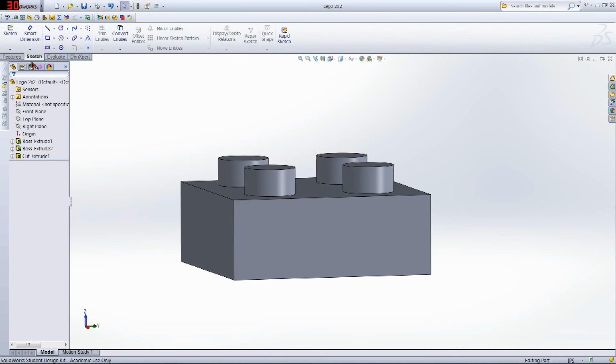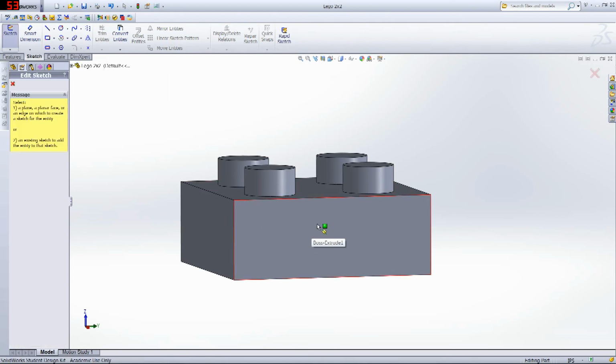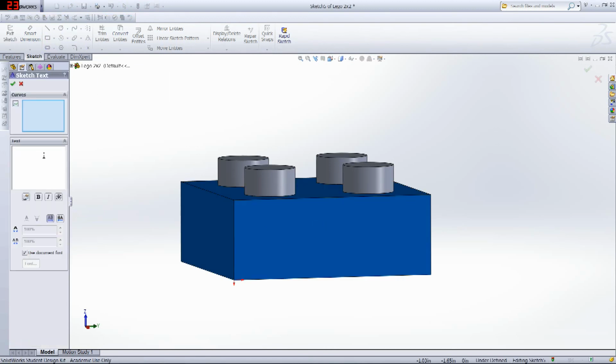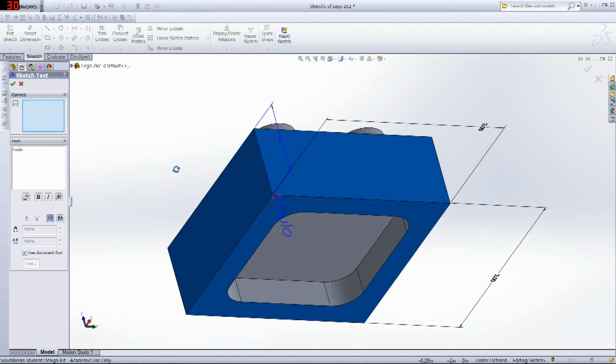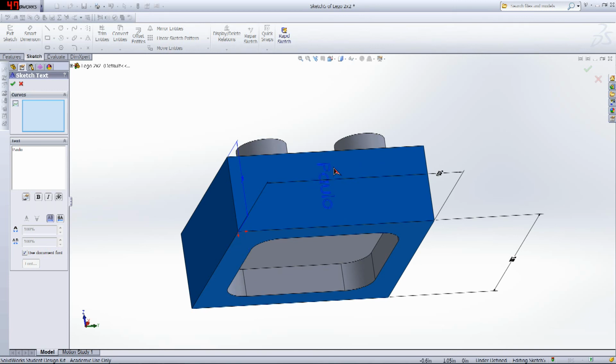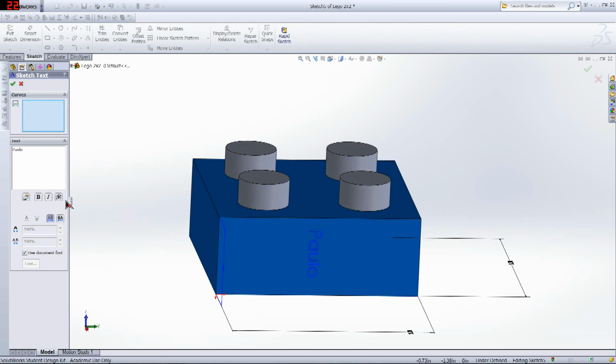Discard. Go to Sketch, hit this little A up here. C means text. Click on the surface you want to write on, and then type in your name, Apollo. It's sideways like this, and there is a way to fix that, but it's not just hitting rotate. Trust me, I wouldn't have tried that. It does that, you see.